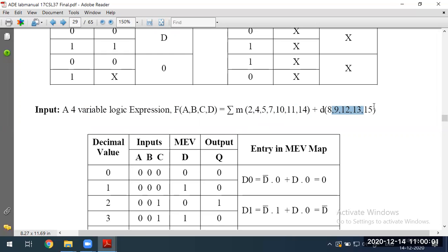It is very simple just to realize. Give the inputs for A, B, C, D as 4 zeros. From that circuit it has to give 0. For 0001, it should give the output low, 0. For the min terms, it should give high output. For the don't care terms, it should give low or high, based on our assumption. And for all others, it should give low output. That is the meaning of the word realize.